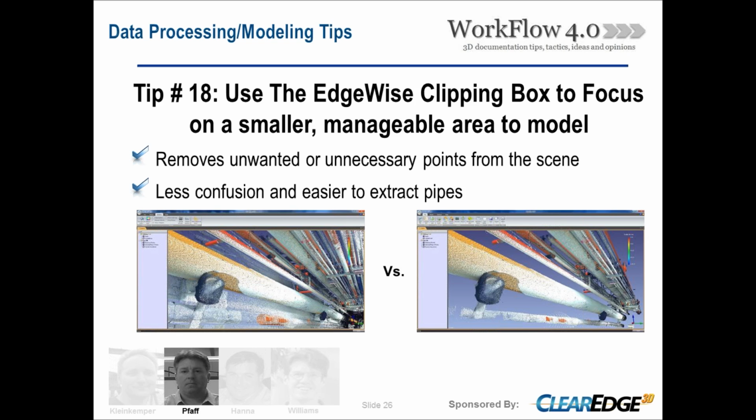Also, I want to mention, back on that last tip, as far as bringing in pipe models, you guys may want to look into using work sets to install your models. We found that when you bring in the piping, a lot of times the client will want it prior to its being through QC, just to have access to what's going on in there.